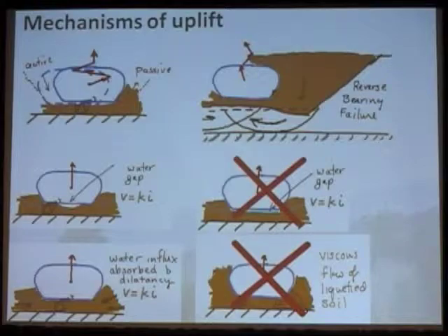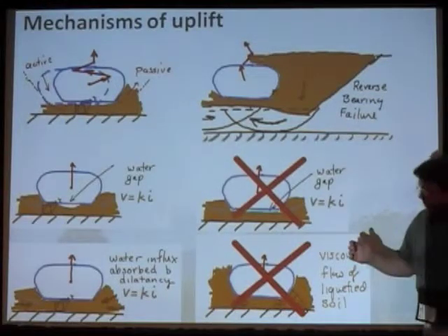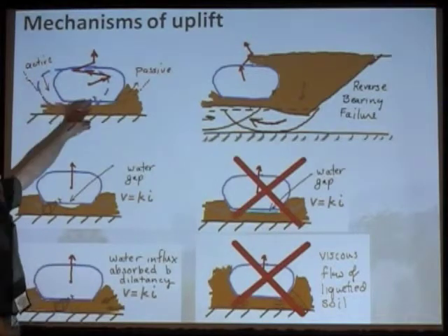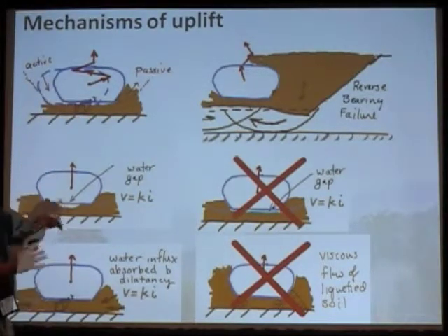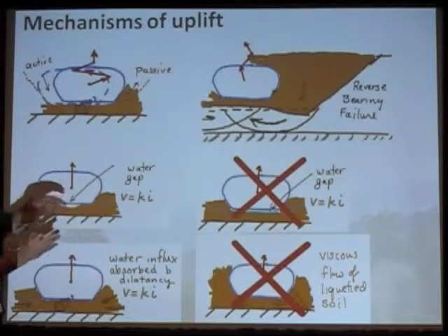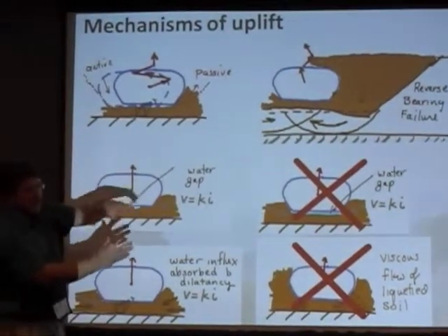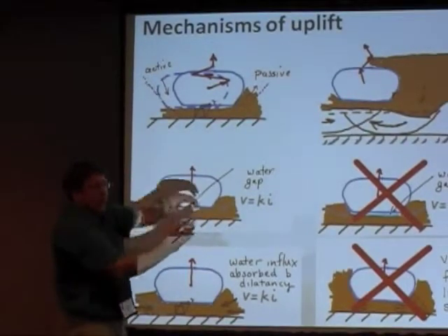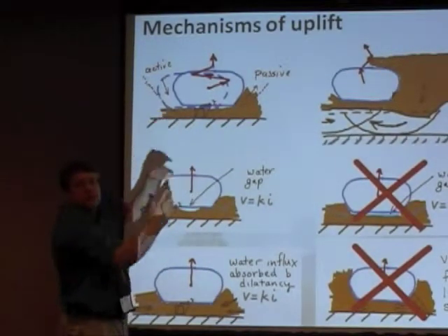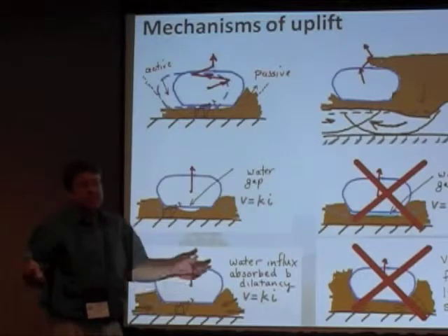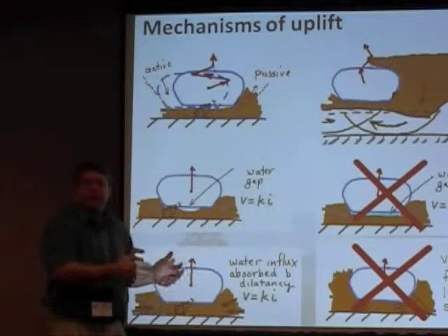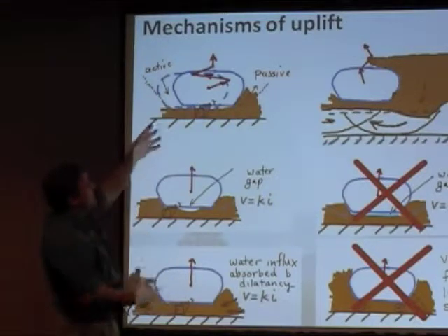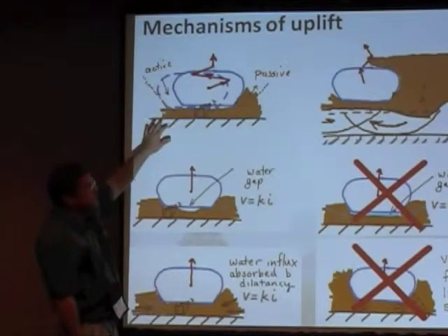So, for example, one way the tube might move is during the earthquake, the tube is going to shift back and forth inside the liquefiable soil. It's going to rock back and forth like that. And as it does that, you can imagine the sand kind of filling in behind the tube each time, and it kind of ratchets its way up. So that's postulated. We think that might happen. So what we want to do during the experiment is we want to measure that. We want to verify, did that happen or not? So we have to think about, how do we measure ratcheting?